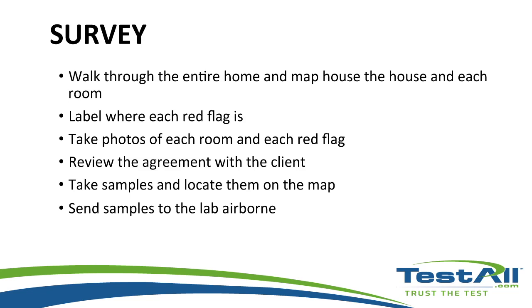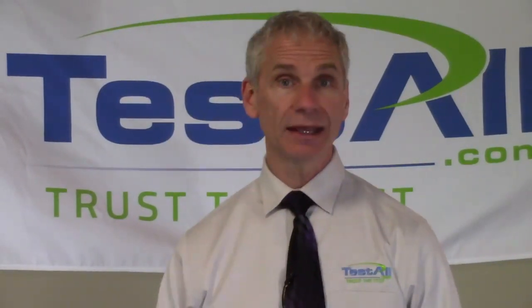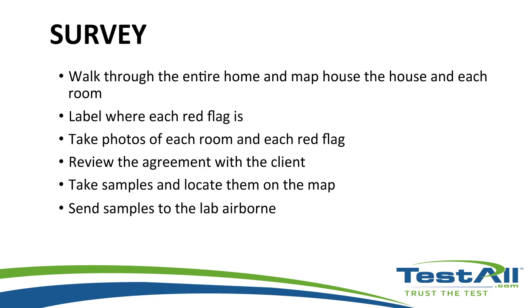Also, it's recommended that you take photos of your sampling. Take photos when you're taking your hygrometer reading so you know what your humidity levels are. Take a picture of your moisture meter if you're putting that up against the surface, and take a picture of your machine while it's running. So you have all of this on a photo in case you ever need it. From there, review the agreement with the client, take your samples, send them to the lab airborne.